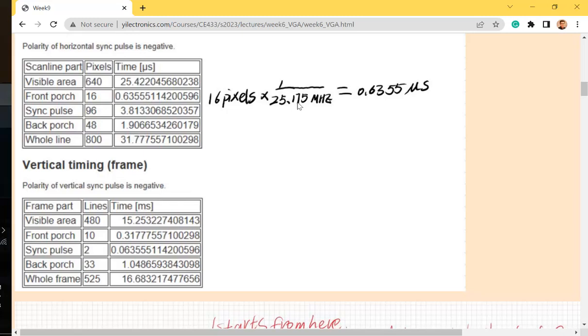One layer down is VLSI, but we don't have to care about the transistors right now. It's all blocks, the gates, or register level actually. That's why it's called RTL, register transfer level language. When you program Verilog, did you program PMOS and NMOS in there? Like programming PMOS on the top in parallel and NMOS in series at the bottom in order to make a NAND gate? You didn't do that. So it gets down to the gate level. Sometimes you use operators like AND or XOR, which are gate level operations, not one layer down.